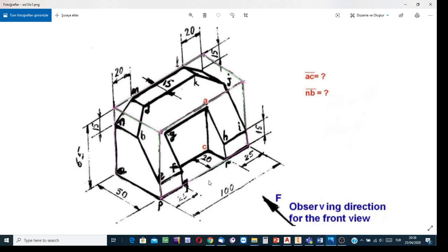Applying this method in real life, from the stock, from the market, we find a rectangular prism. It is the minimum to be in the overall size of the object. Okay, and then after taking such a rectangular prismatic block, put it onto the table of the shaping machine, and then cut the unnecessary parts, trim the rectangular prismatic block, and set the shape of the object. In real life, rectangular prism and then trim, cut this part, have this channel. Cut the material, create this surface, cut the material, create that surface, you know.